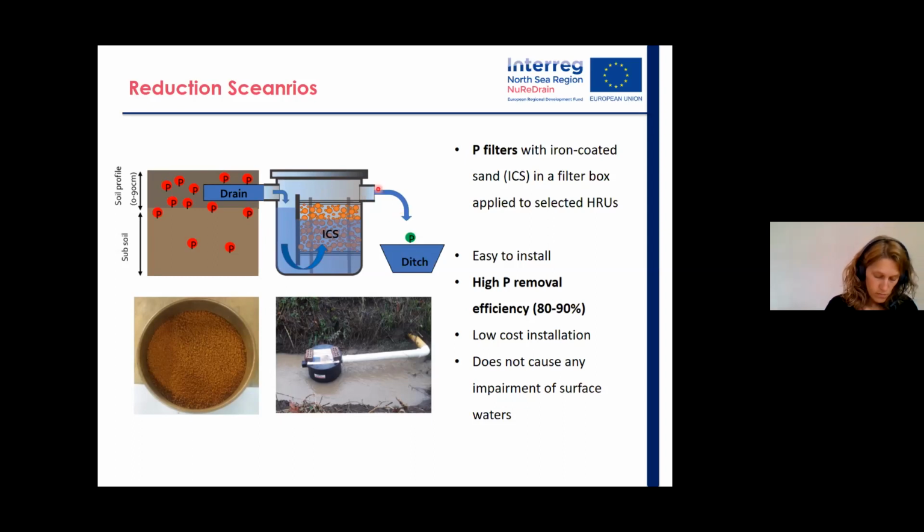The advantages of these filters are that they are easy to install and they show a high P removal efficiency with 80 to 90% P removal. It is a low-cost installation, and a very big advantage is that these filters do not cause any impairment of surface waters at all. So these were implemented into the model input